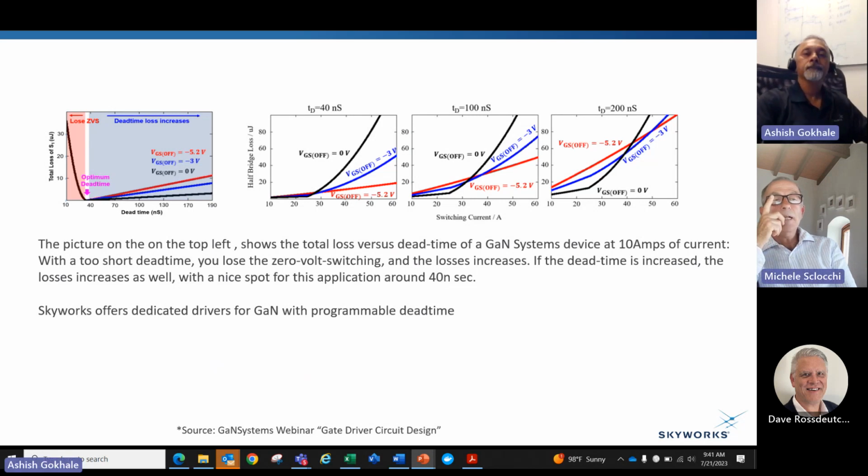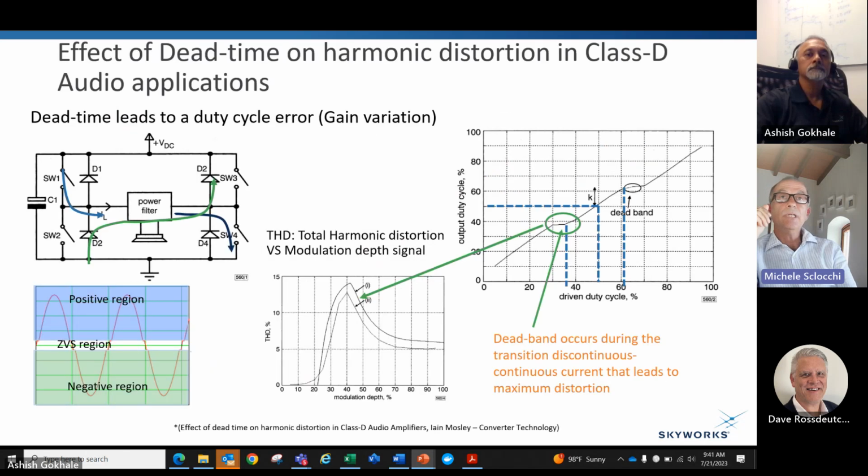Thank you. Let me just add another comment regarding dead time. With GaN technology, we have a lot of design going on in Class D audio, and several customers point out that the dead time is very important to reduce the total harmonic distortion, I mean, to improve the audio performance of their amplifier.